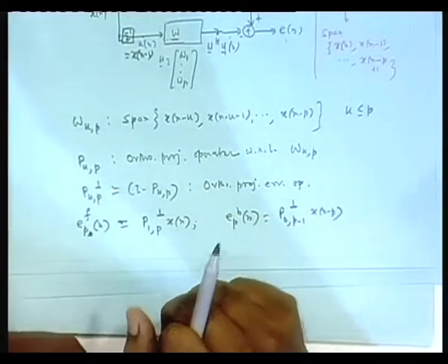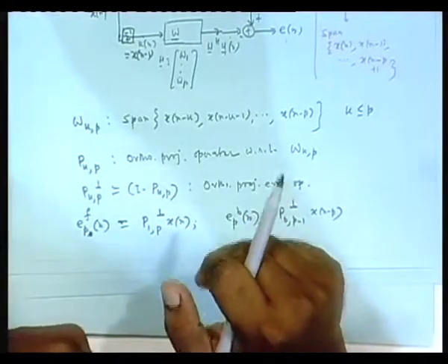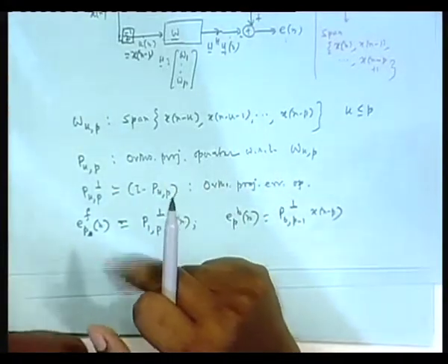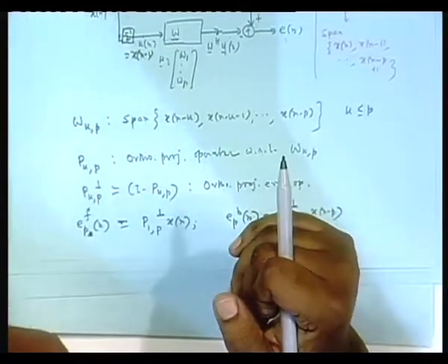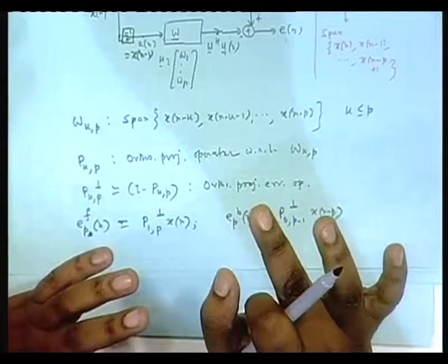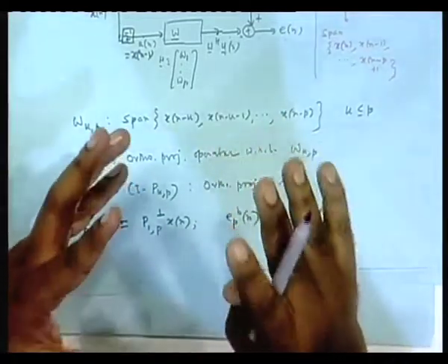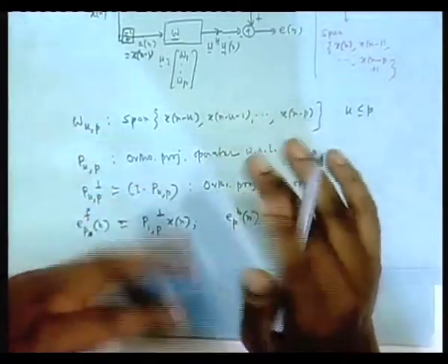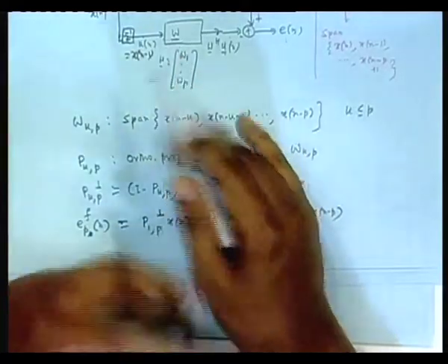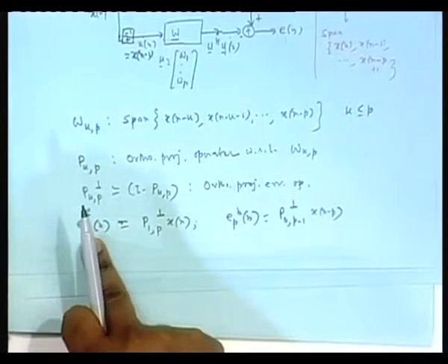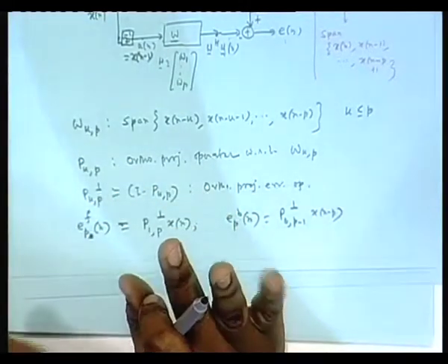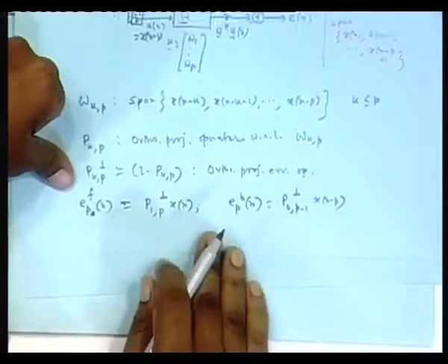The moment I take expected value, there is the norm square, there is the variance. Because of stationarity of xn, all those multiplying terms become independent of n, isn't it? You get some elements where linear combiner coefficients will be present and correlation terms will be present, but nothing of n. So, that means the norm square of this guy, the variance of this guy, is also independent of n. So, in the notation, I can drop n.